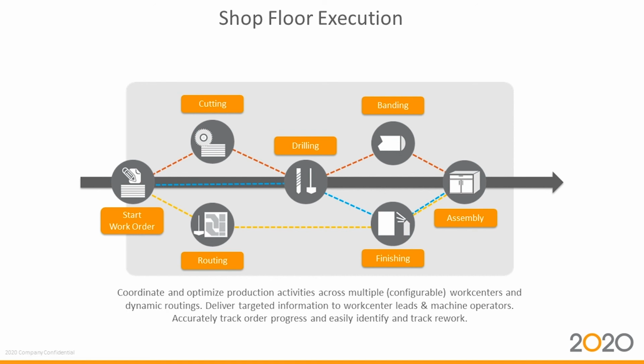So let's assume we have enough material and work orders are created. The system will now automatically release everything into the shop, and based on my schedule, I can see the capacity I have available in certain work centers. If one machine, for example, breaks down, I can move these components to another machine by dragging and dropping those work orders into the other machine center, and the system will recalculate the new CNC code for that machine, because the new machine may have a different tool setup and so on. But mainly the routings are there for guiding the individual parts through the shop.